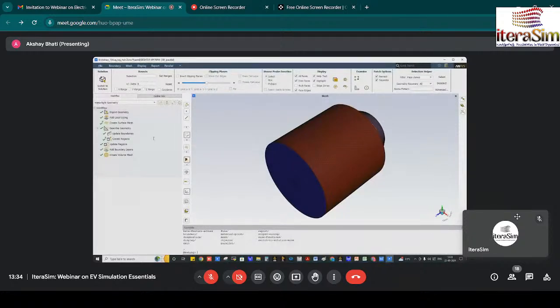I modeled additive friction stir deposition. The material flow behaves like a fluid flow, so I am modeling it using an SPH model, where the FEM elements change to particles.